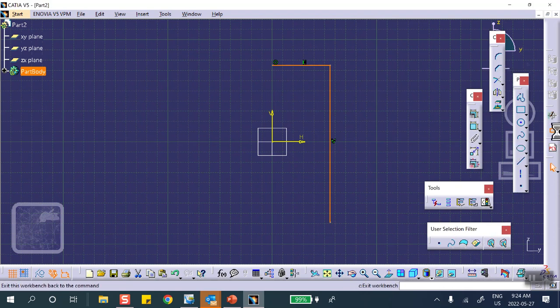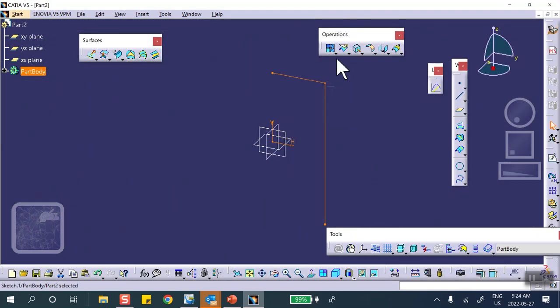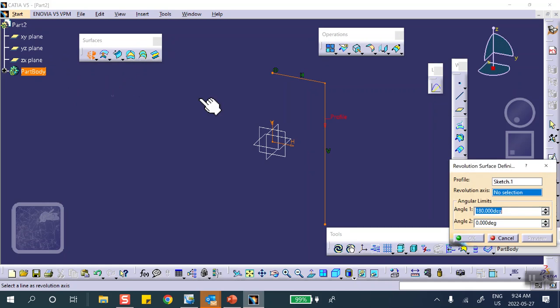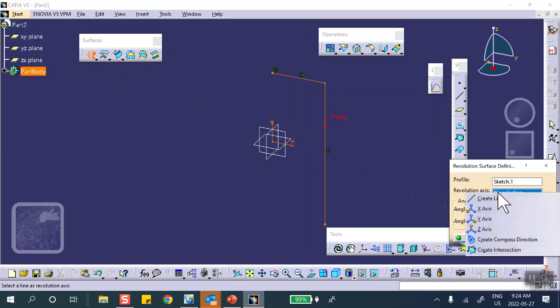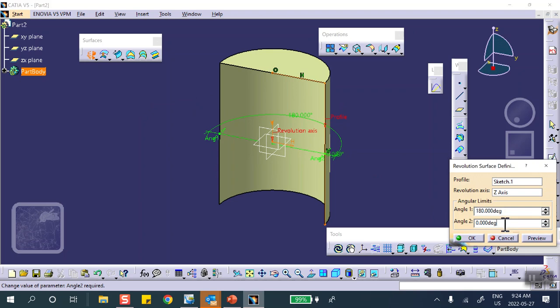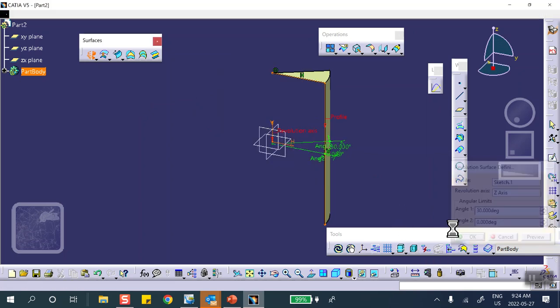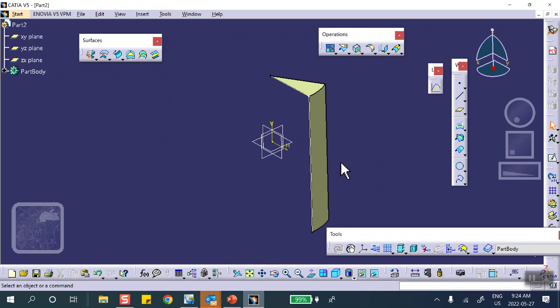and revolve it. CATIA does not call this thing shaft. In generative shape design, it calls it revolve. See, these are different ways of making surfaces. We have already done extrude, and there's one here which says revolve. So it says revolve this about the z-axis. By how many degrees do you want? Let's say 30 degrees. You don't have to join these. Just like when I extruded, I got a single surface. You just revolve it. The rest of the problem is exactly the same. So let me stop this recording first of all, and then I talk about